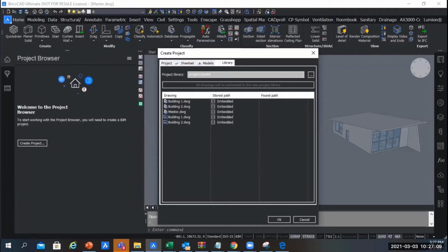The .bclib. Lib stands for library, systems library. Afterwards, all the drawings will share the same library. If you, for example, make a custom property, which you have seen in Ken's presentation, then that will be stored in your .bclib. Okay, important. These properties will also show up in other drawings and vice versa. Therefore, it is important that the entire project shares the same .bclib.